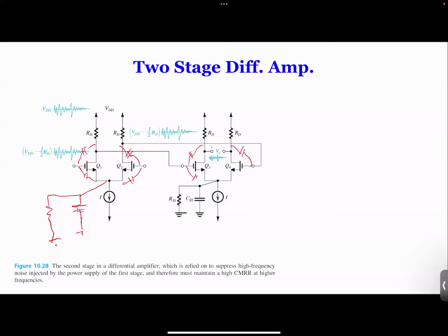So you control all the capacitance, everything. All these capacitances are internal to the devices, and they make a huge difference at high frequency because they start to show impedance in your circuit, right? So in this example, the book briefly discussed, I thought it's very interesting, that sometimes in a power supply, VDD, you have a noise, and which is true.